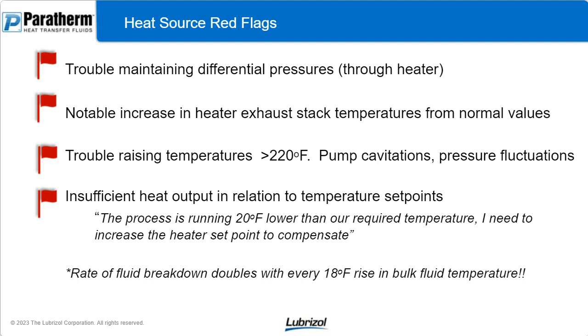If there's a notable increase in that exhaust stack temperature from what it normally is, that's a red flag. Question that. If that heat energy that used to go into the fluid, used to go out into the system, is now escaping through the stack, something is prohibiting it from going into the fluid, and that needs to be checked. It doesn't just happen on its own.